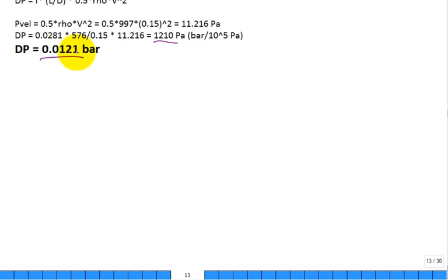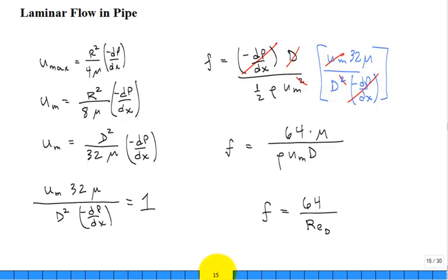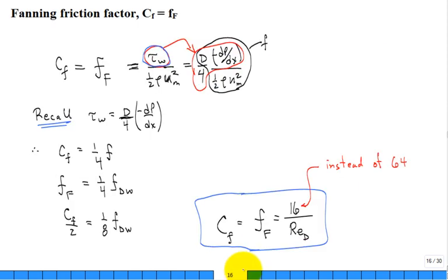All right. That was all fluids. You can get this equation, the friction factor, 64 over Reynolds number. It's more algebra, just repackaging. Okay? So done with that. You can, again, emphasize the difference between the Fanning and the Darcy friction factor, that factor of 4. And often the red flag is if you see, in the Moody diagram, 16 over Reynolds number in that laminar region, you know that's a different friction factor. It's not 64.